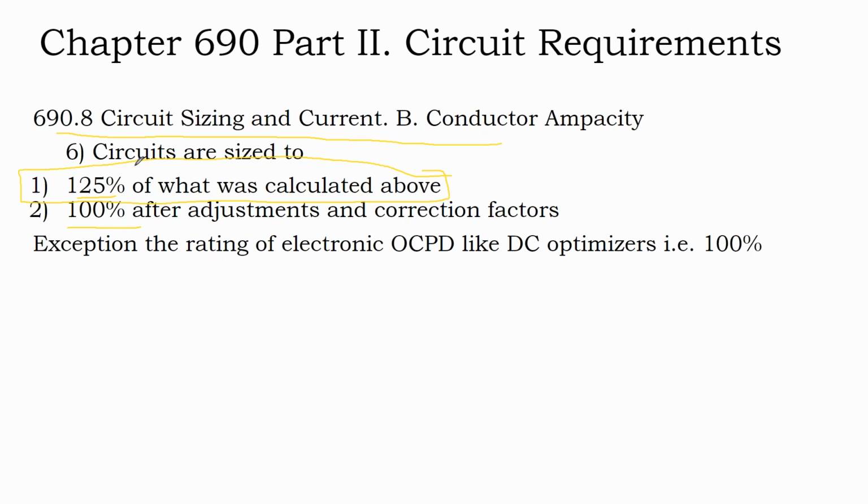And so what code is saying is either you're taking the listed amperage for short circuit current and adding 25% to that, and then adding another 25% to that, which means, whatever the amperage is of the circuit, you're adding an additional 56% and just treating it like that's the amperage of the circuit. So you're just giving yourself tons and tons of headroom in your conductor for that electricity. Or you go through a series of temperature correction factors similar to what you do with voltage.